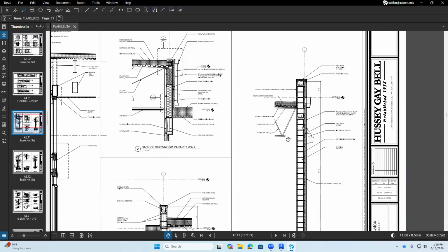Now, if it's a concrete wall, a CMU wall, we'll have a concrete lintel because obviously it's going to be heavy. If it's wood framing or metal framing, we may have a wood header over there. Essentially it serves the same purpose: distribute the weight of the wall above away from the door frame and put it back on the sides. That's the purpose of a lintel.